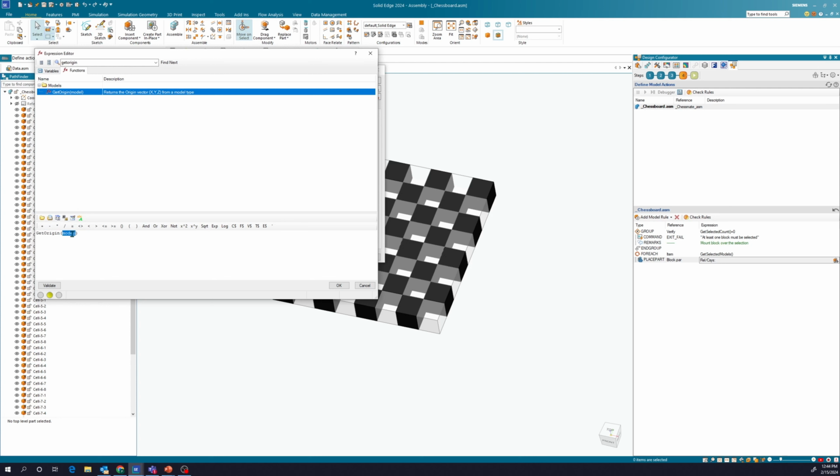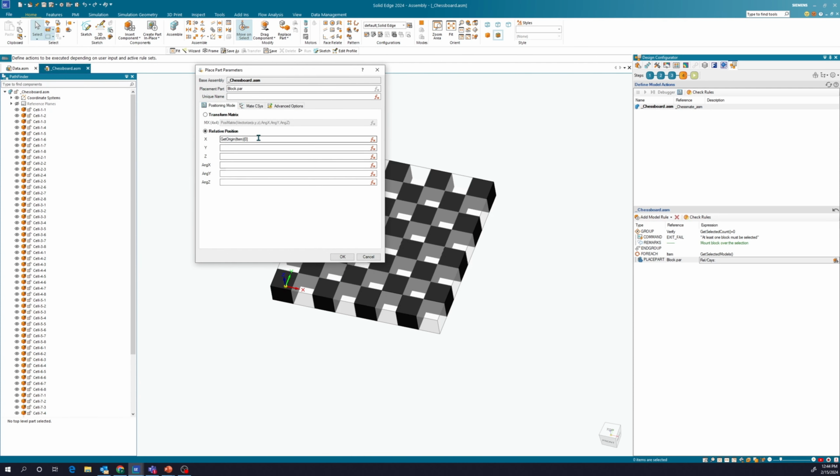In here, instead of model, I'll change the model name to item because that's what is shown right here inside the for each loop, it says item, and place it at the origin. So here, all I'm doing is just specifying the location. Also, I have the option to copy paste the relative position for X, Y, and Z. So this becomes 1 and this one becomes 2, and I want to move it by 100.